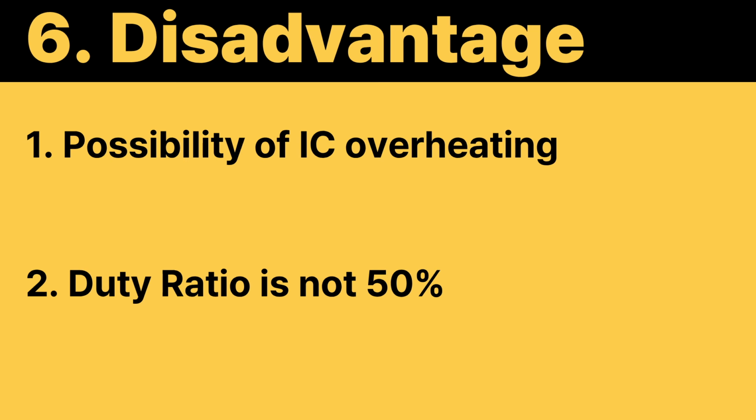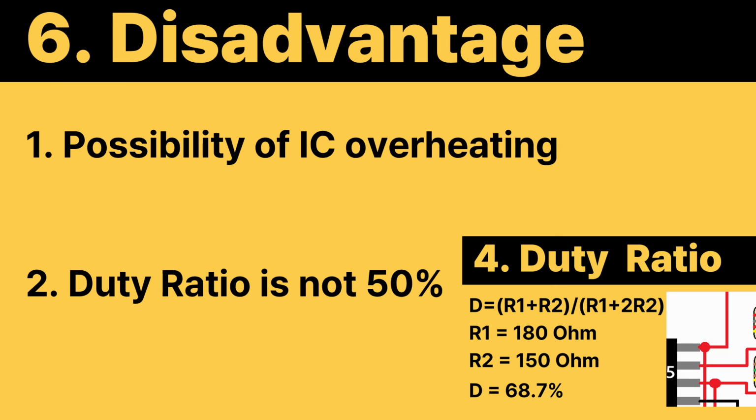Next, the disadvantages. Potential for IC heat generation. 30 kHz may be strenuous for the standard NE555, and the duty cycle is not 50%. If it's not 50%, the waveform can be asymmetrical. To solve this, you may need to recalculate the resistor values.